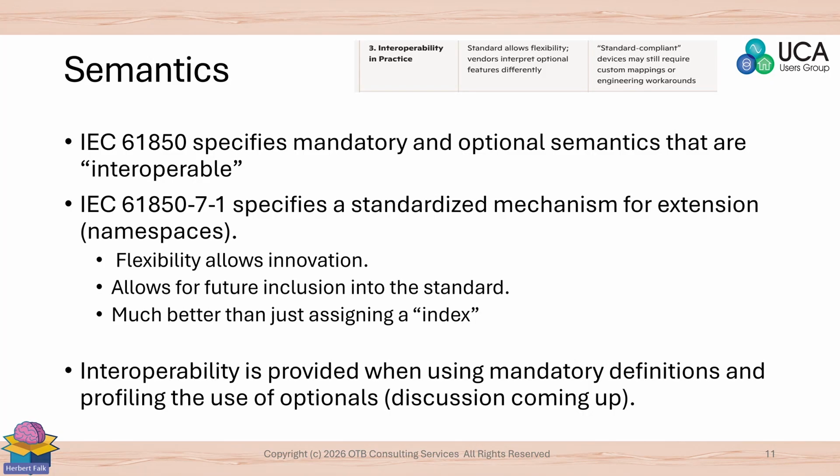It's true that 61850 specifies mandatory and optional semantics. The optional semantics in the standard are very well defined. It's just a question of whether a vendor implements that semantic. And if the vendor wants to do an extension, 61850-7-1 specifies a standardized mechanism for extending it.